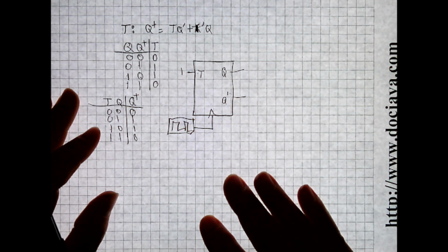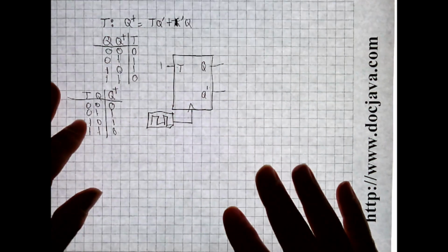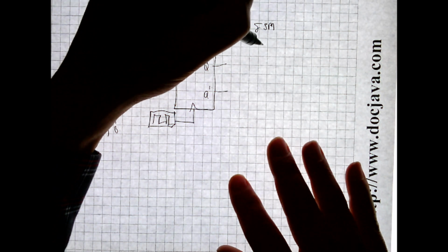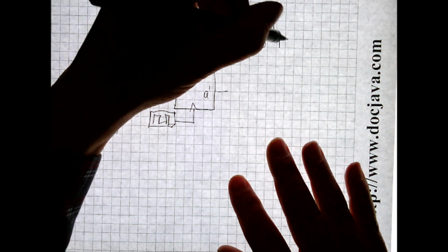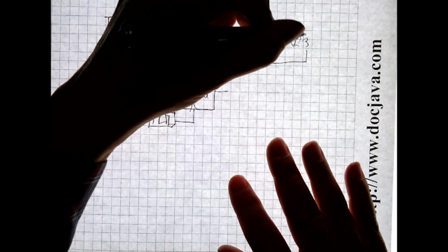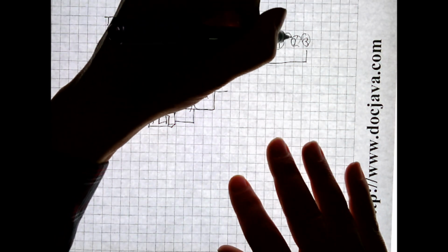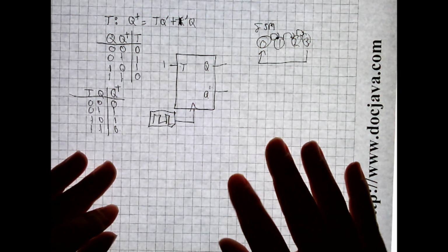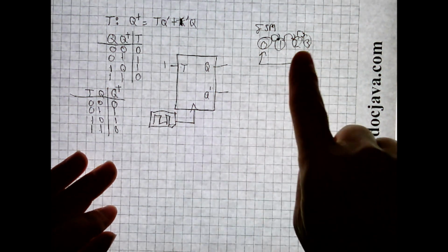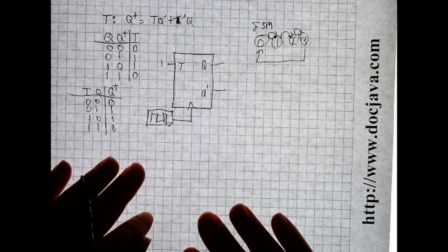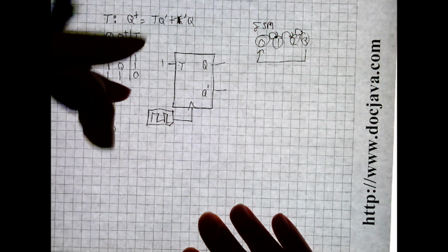And so now, let's repeat the experiment where we create a finite state machine given the following finite state machine diagram: 0, 1, 2, 3, back to the beginning. Find a design using toggle flip-flops to implement the following finite state machine. So just like before, you do a present state, next state diagram.